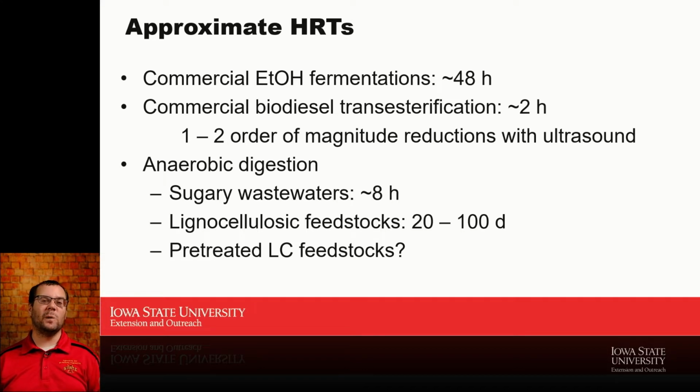If I move towards manures and other agricultural residues, I'm really looking more at that 20 to 60 day window, in some cases maybe even longer. And then there are various treatments that people are studying to try and speed that process up. I won't tell you that we have it figured out, but we do know that grinding things up, of course, makes the process go faster, and we're trying to balance how much we have to grind to how much hydraulic retention time that improves for us, and does it lower our overall carbon footprint? Does it change the process economics enough to justify doing it? So that is an active area of study for anaerobic digesters, and where people are still trying to make some improvements.